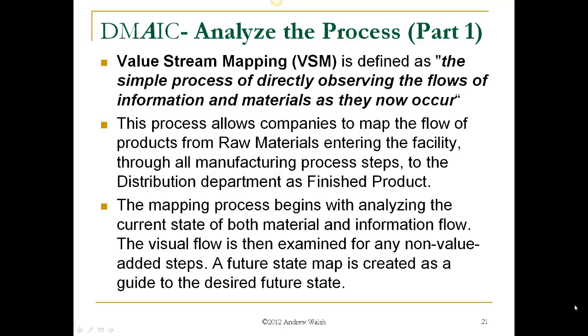Now, the mapping process begins with analyzing the current state of both material and information flow. This visual flow is then examined for any non-value-added steps, and from there a future state map is created as a guide to the desired future state of the process.